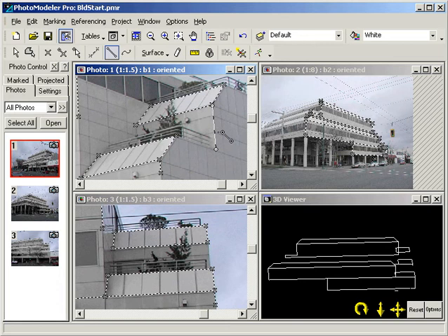The importance of an edge does not lie in where its start and end points are, but where the position of the edge line is. The start and end point positions of matching edges across photos do not need to match. You can estimate the endpoints of edges in order to do the modeling you need. A short edge can be referenced to a long edge as long as the lines match up. The final length of the edge is determined by the longest edge that is marked in the photos.